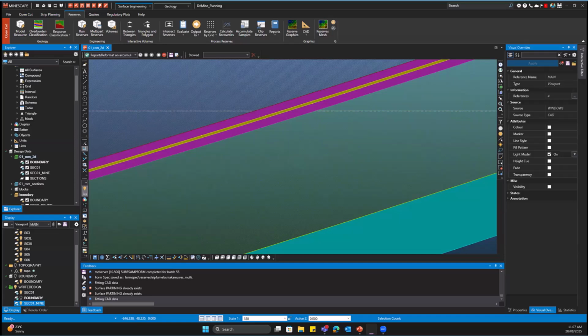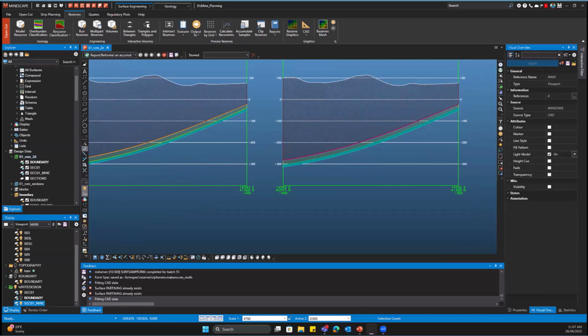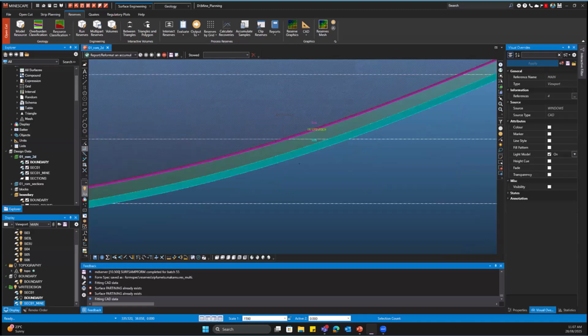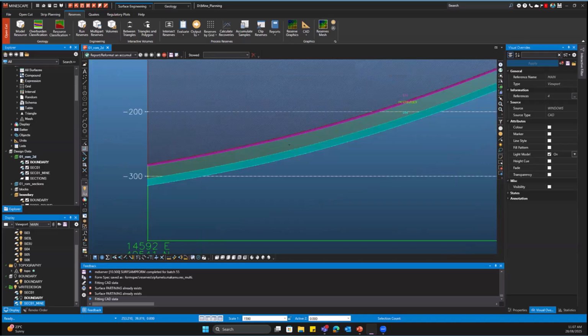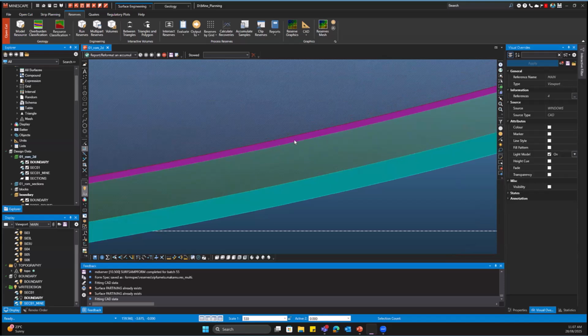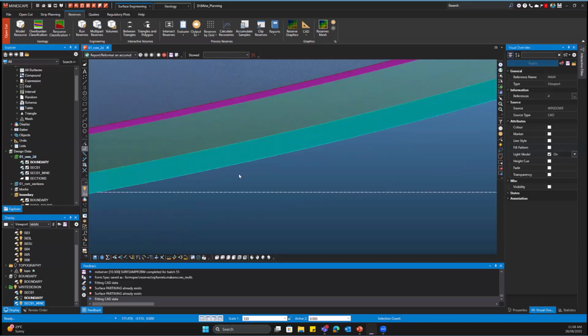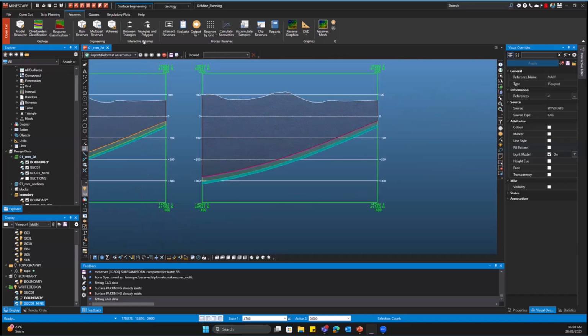When we look at how it's going to play out when we apply our mineable interval, you can see we still have the overburden. Then we have applied our mining interval, saying we're going to mine this including that parting because it's so small, but we need to be able to calculate that dilution and know what the dilution is for that interval. And we have the next interval, which is seam 6, that we are going to mine. In this case, we have seam 6 that we're going to look at, and seam 5. Right, cool. So I'll proceed and go to the software.